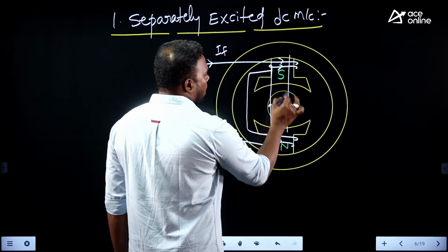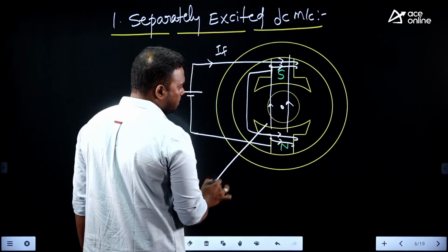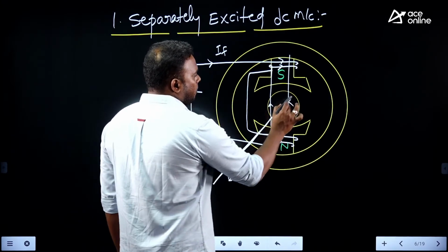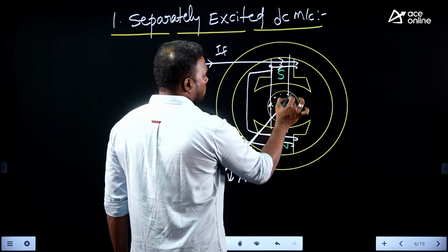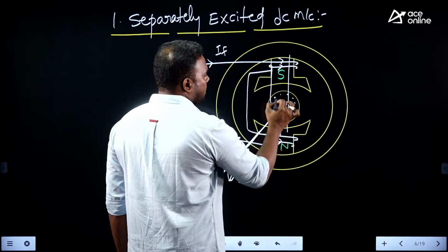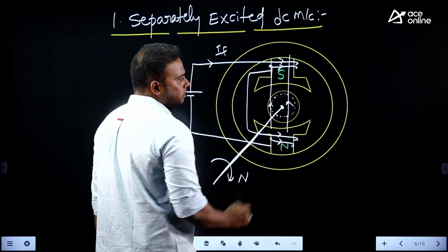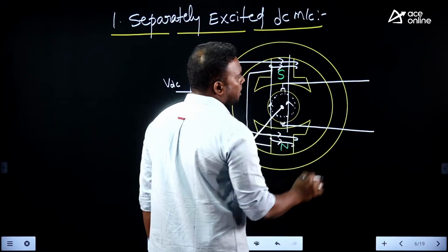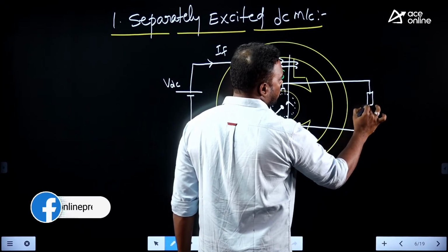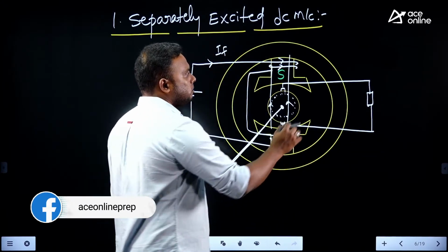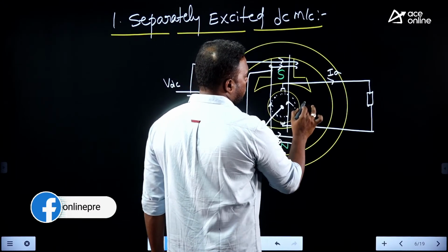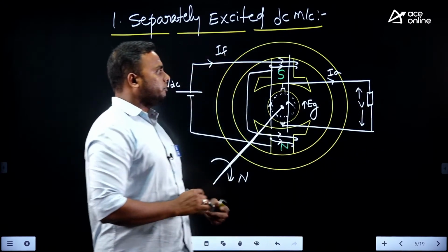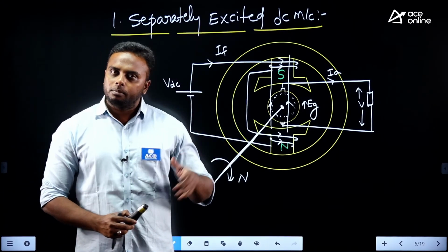Okay, and this is our armature. I am considering it is a generator. Generator means we need to rotate it with a prime mover in some direction at a speed n. Whenever it is rotating, there is an armature winding inside the rotor, or armature core as we call it. This armature winding will cut the flux passing here, then an EMF is induced, and that EMF we take outside through these brushes. Whatever EMF is induced will come to the load. Once we connect a load, a current will flow, the armature current, with induced EMF EG, and the terminal voltage is V. Terminal voltage is V.